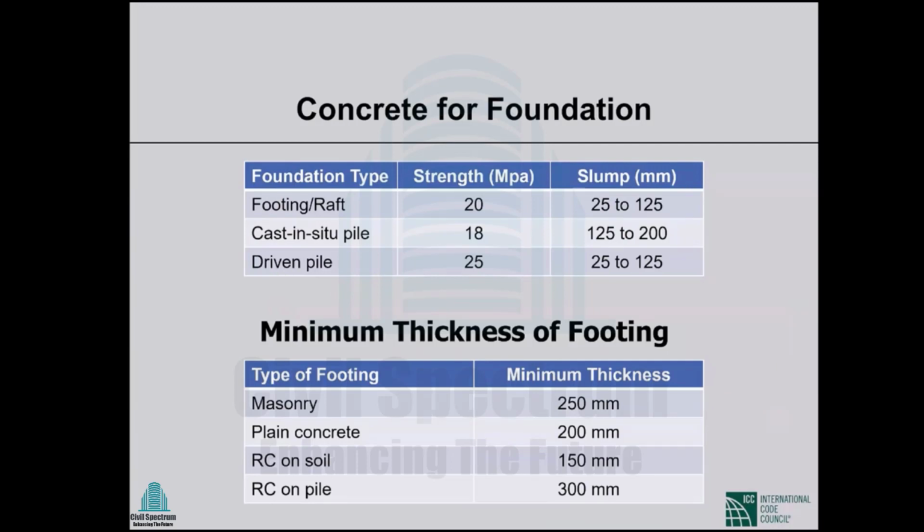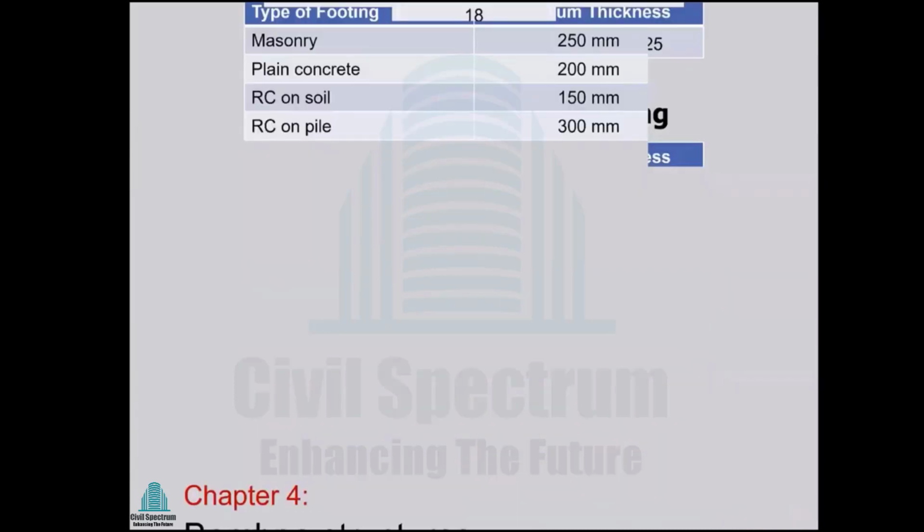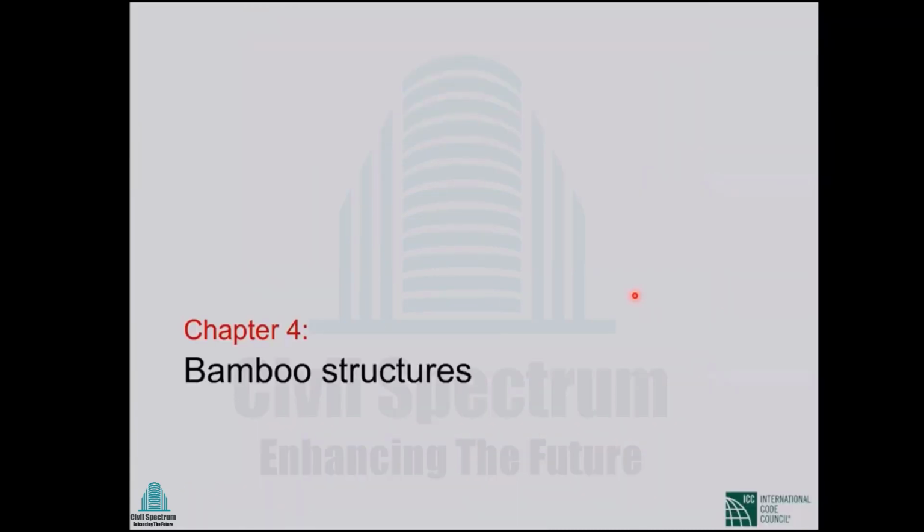Minimum thickness of footing, I think you shouldn't stick to these. Actually, you have to calculate the thickness. So that's it. Chapter 3 has a lot of things, and a number of appendices are related to chapter 3. So that will be covered by Professor Abedin and Professor Ansari.